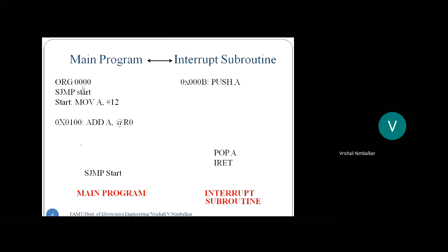Now the main program, the program which begins from 000 hex, is the main program. Whenever you do your projects, the microcontroller will always keep on executing the main program. So it is in an unconditional, unending loop. Correct? Whatever project we do, that project should run 24/7. So that main program is always in a while loop, an unconditional, never-ending loop. And the program is the one which begins with 000 hex.